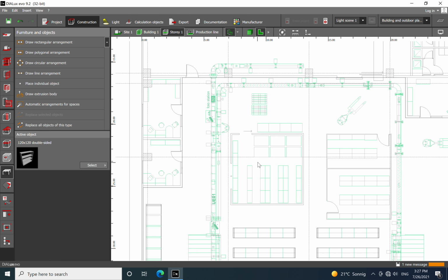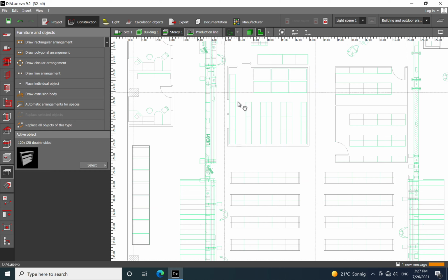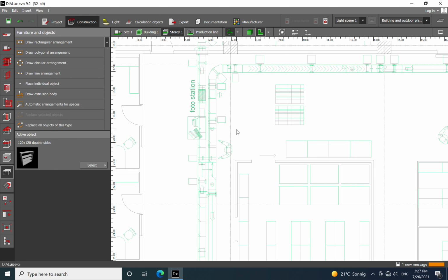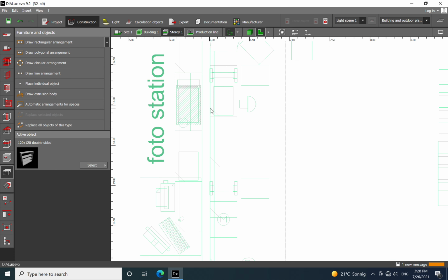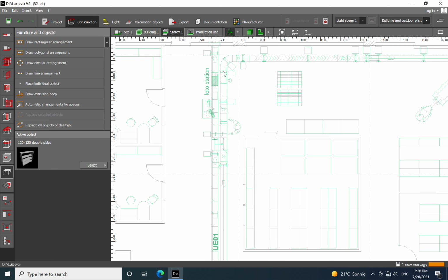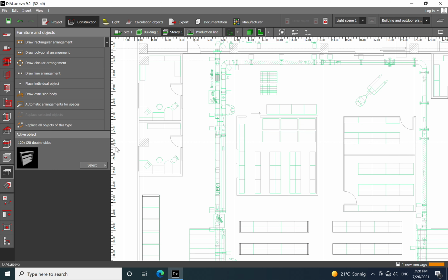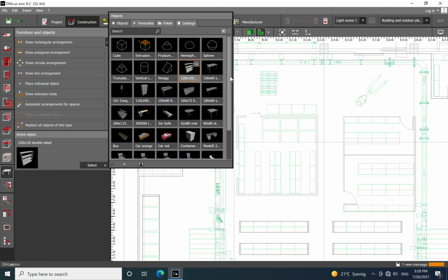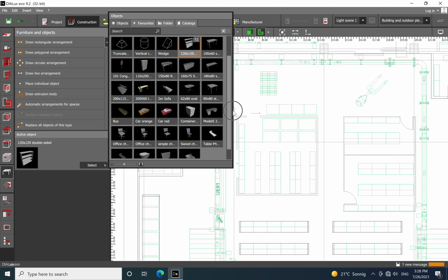from Dialux. Actually, even I know that I don't have a conveyor or a continuous line. I will say that what is important is the height and the dimension, and you can just use, for example, a table and scale it to represent the actual conveyor size.